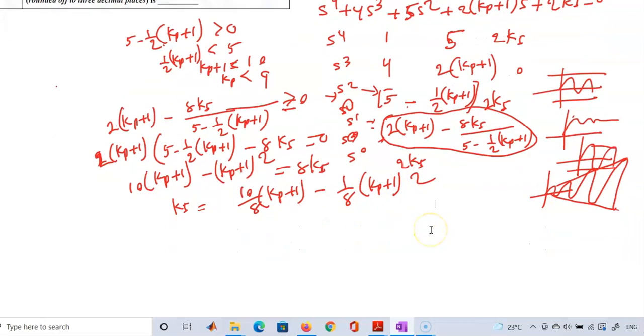So we need to find the maximum value of ki, and you know the theory of maxima. So we normally take the derivative of ki with respect to kp. Why kp? Because ki is a function of kp. The value of kp should obviously be less than 9. Otherwise, the second row will also be 0. That will create another problem, a double pole at the imaginary axis.